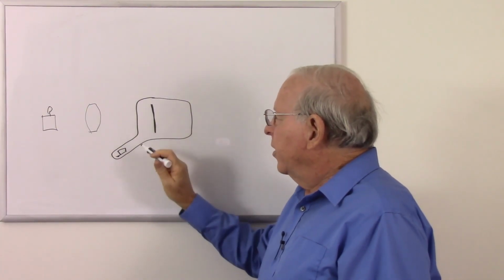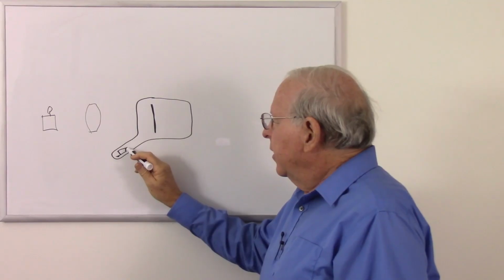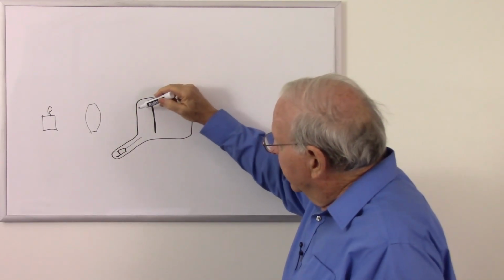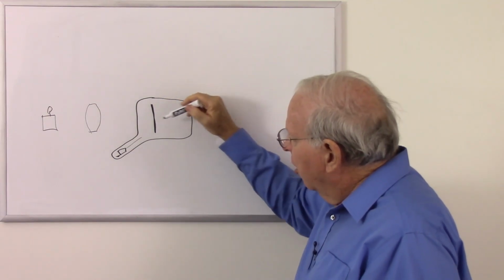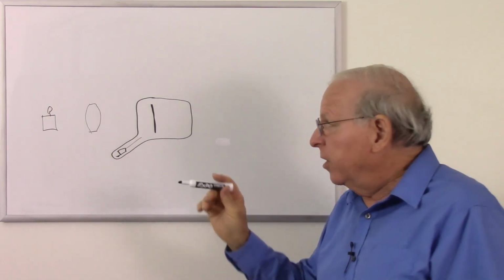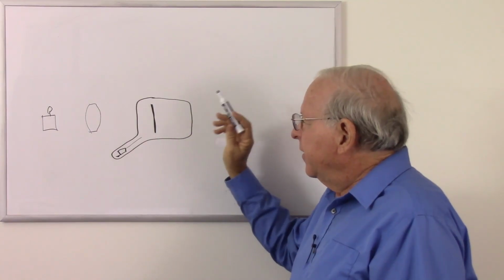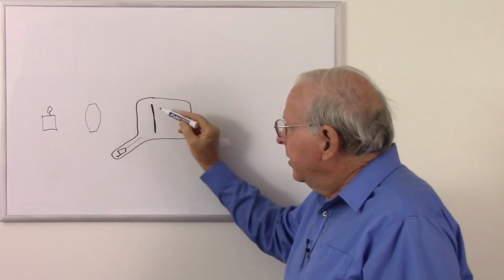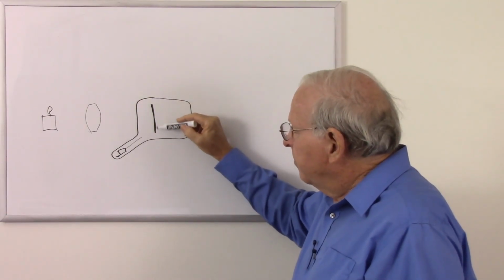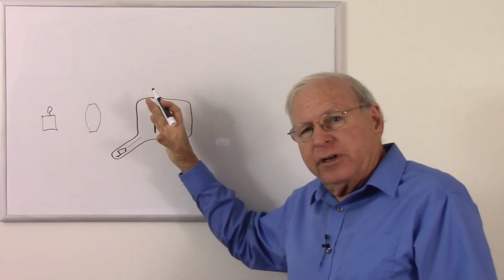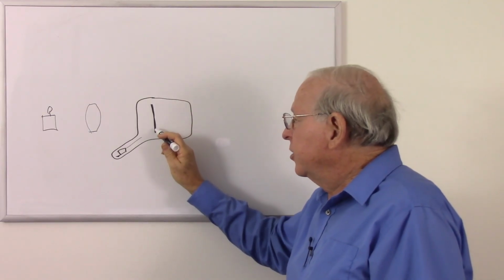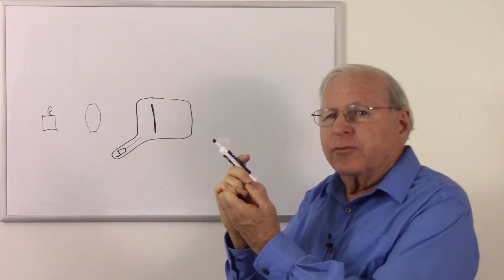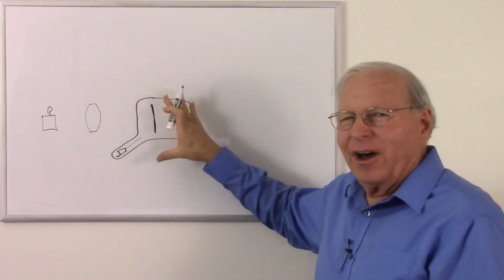So we have our image going in there, and first they would use the electron beam at high velocity, and they would scan across this to charge all those little capacitors, if you will, with charge. And then they would turn off the beam, and the light coming in would discharge some of those capacitors. The more light, the more it would discharge. So we ended up with an image on these materials that was less charge where more light hit. So it's kind of an electron negative image.